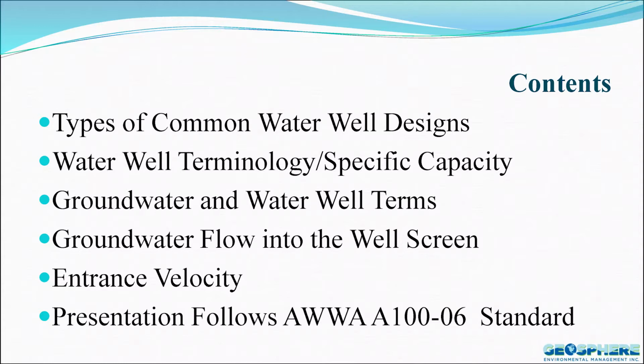One really important thing, which Ted touched upon a little bit, is groundwater flow into the well screen, why it's important, and why we need to know what it is. A term which people don't think too much about unless you're actually designing wells is the entrance velocity of that particle of water entering the well screen. All of the things that I want to talk about follow the AWWA, American Water Works Association, A100-06 standard, so that everyone can follow this no matter where you are in the US or around the world.